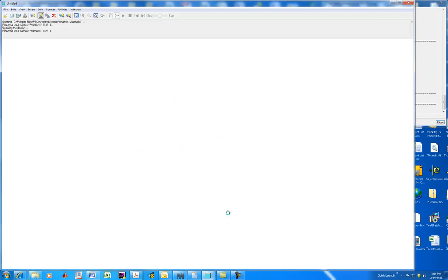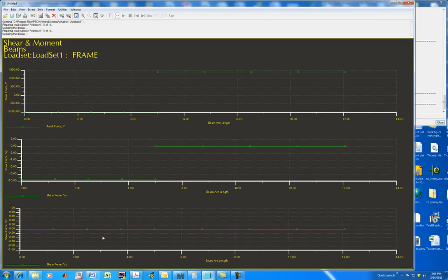We will OK and show. And so our shear force in the Z direction, that's out of the plane. That's pure 0. Our shear force in the Y direction for this one is going to be a constant on the cantilevered beam, and there would be no shear possible on the 2-force member. And we're going to have an axial force on the 2-force member that's fairly high. It's at the 45 degrees, and we will have an axial force on our member that's cantilevered.